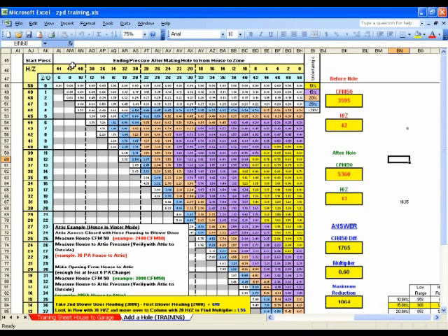Numbers going across are pressures after adding the hole. We started out at 42, and we move across to our pressure after adding the hole, which is 13, and we come up with a multiplier of 0.6. So this is telling us our maximum reduction possible is 1064. Our blower door number was starting out at about 3,600, and we can reduce it by over 1,000 if we seal those leaks between the house and the attic. So pretty significant.